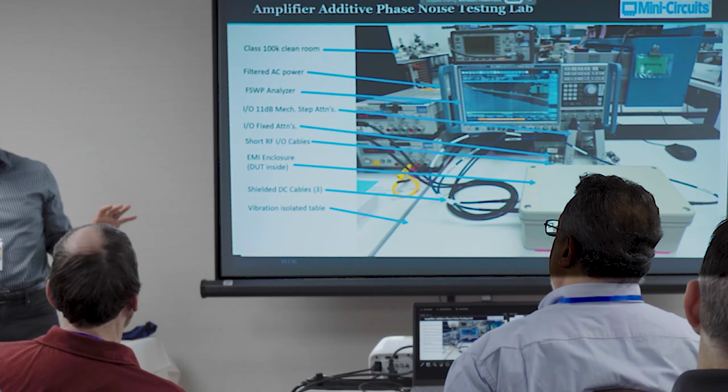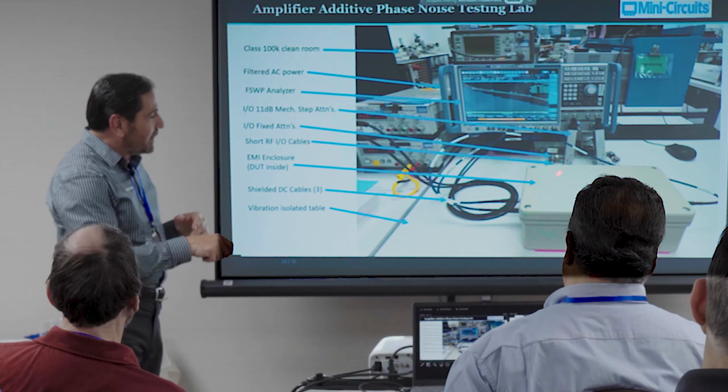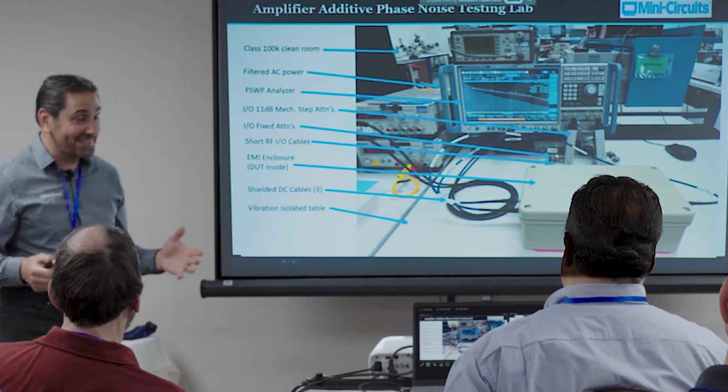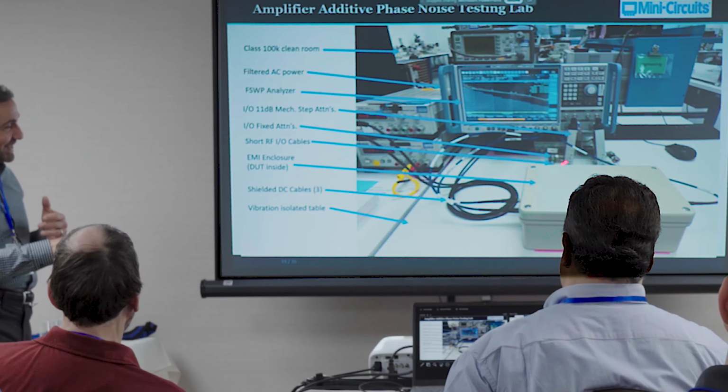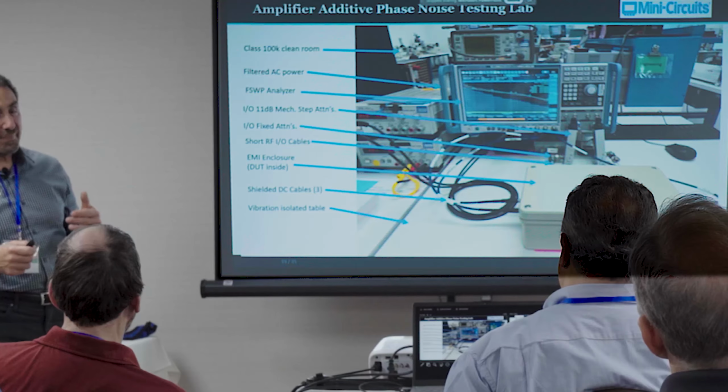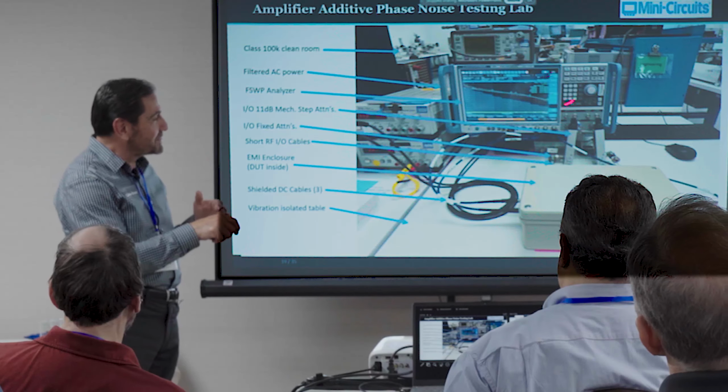That's it. I'm not touching it. I'm going to use my 11 dB, 1 dB step Keysight attenuators to vary, and my fixed pads here, to set the input power dynamic range to my device. So I use these now. I don't use the instrument.